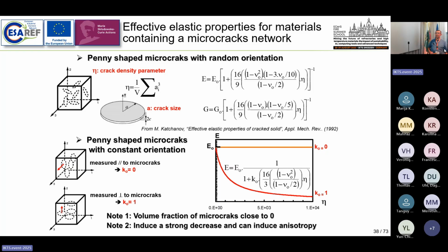The formulas are quite complex. But of course, you have seen from Dietmar the R''' parameter, the thermal shock parameter from Hasselman. Behind this R''', there is this formulation of the evolution of Young's modulus. If you look at the original paper in the 60s, you have exactly this formulation, which is taken into account in an energetic balance of Hasselman. The formulations are not so simple, but not so complex.